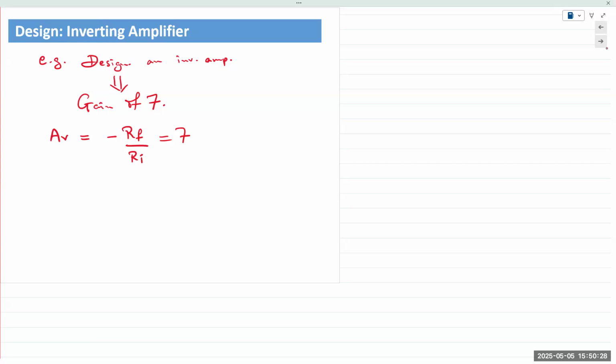Anytime current flows through a circuit, energy is transferred. A lot of the energy is dissipated as heat, lost as thermal energy. So our devices get hot. That's why every component comes with a power rating. Most resistors that we use have a 1/4 watt power rating. That's 250 milliwatts. So in a real-life design, we would have to take all of these into account.